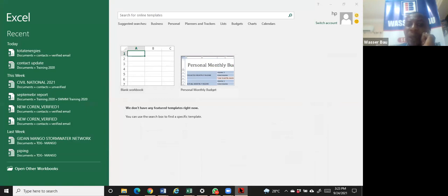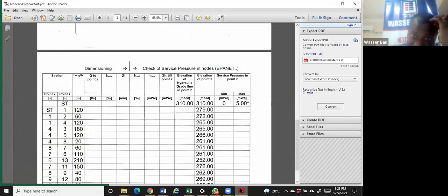And that was why in our lecture yesterday, my colleague told us that after you have done your mapping, the next thing is you do your water demand determination. You do your population projection to get the exact number to use. And I say it again, if you are designing for a 50-year lifespan, it is the population after 50 years that you use. That is why you need to project your population to the future, and also project your rate of development to the future. And that is why the issue of land use is very, very important.